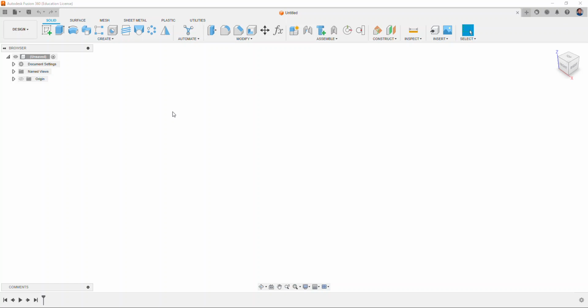Hello everyone, we're going to go ahead and take a look at a different technique of how to create our construction blocks in Fusion 360. This is using a little bit more of what they call a top-down modeling method. If you look at some of my other videos, I do a bottom-up modeling method where every block has its own design file. Right now we're going to have an untitled design file, and I'm going to create multiple models within this, or components.